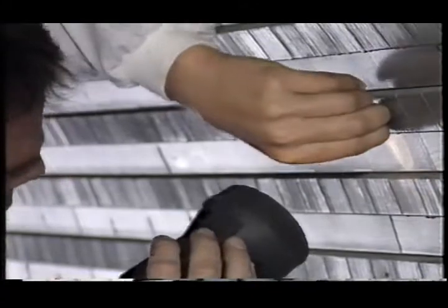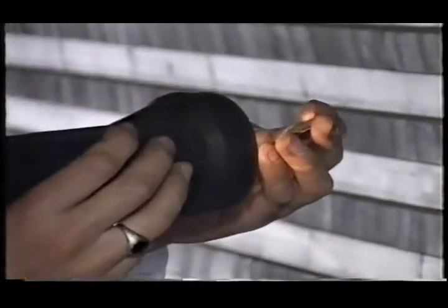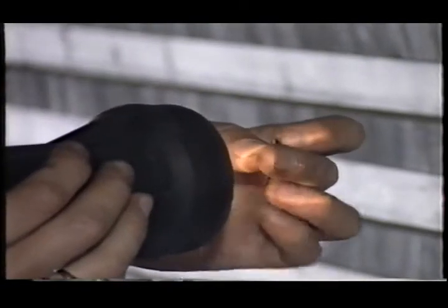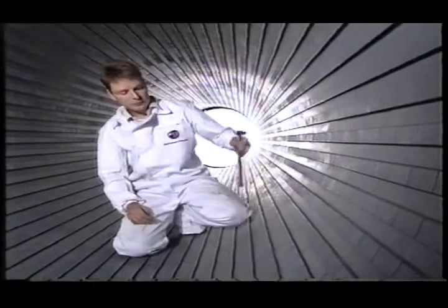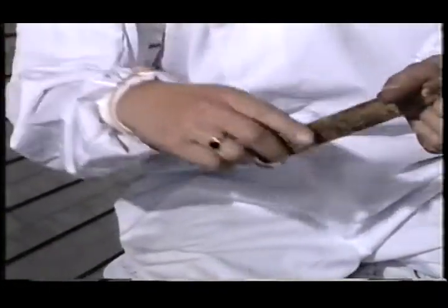It's not only foreign material left in the machine that can cause damage. Debris such as small pieces of core plate and vent spacers can become detached from the machine itself. To avoid losing tools, where possible, they should be attached with a wrist strap.